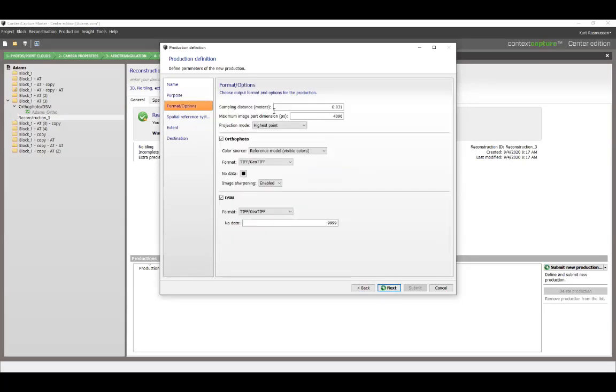And then when you go through here, there's a sampling distance. And this is something I wouldn't guide somebody to do it this way. This is the way that was built in the software, but it's actually going to make your 3D mesh and then flatten the 3D mesh, which can cause some edges of buildings, like roof edges, not to look very crisp and clean.